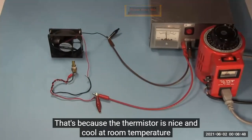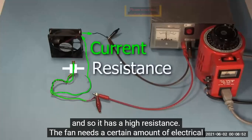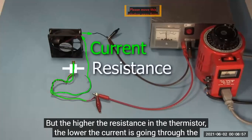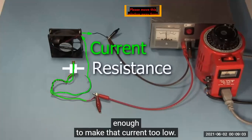That's because the thermistor is nice and cool at room temperature, and so it has a high resistance. The fan needs a certain amount of electrical current going through it in order to spin. But the higher the resistance in the thermistor, the lower the current is going through the fan, and the resistance of the thermistor is high enough to make that current too low.